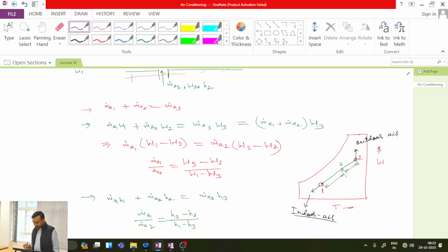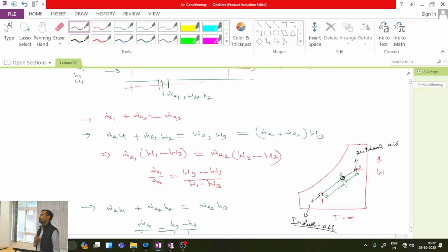So that is the reason when I have added outdoor air, the overall humidity is not exactly equal to outdoor air nor is it equal to indoor air. So the total humidity has reached some point 3. Now after this mixing, I need a cooling coil which can further decrease humidity from 3 to 1. Is this point clear? So it means that this mixing of ambient air actually creates additional load on the air conditioning apparatus. How it creates additional load, you need not worry now. Right now I am only explaining the basic processes.